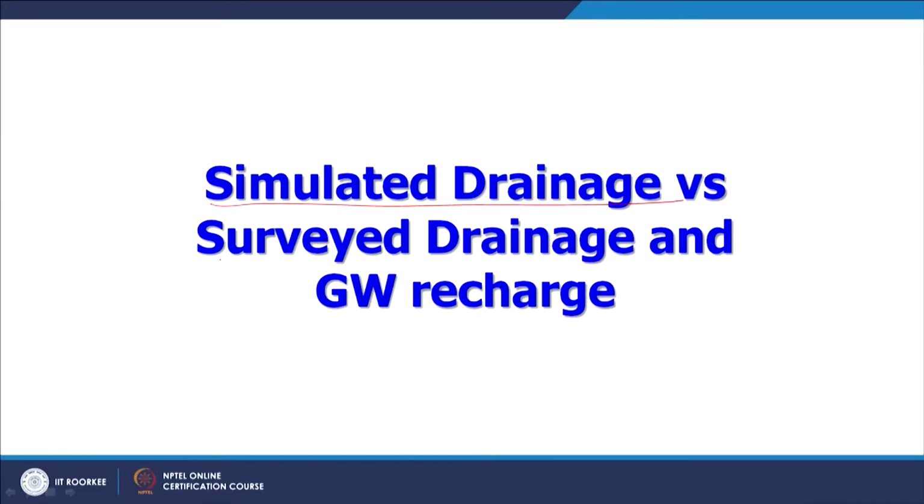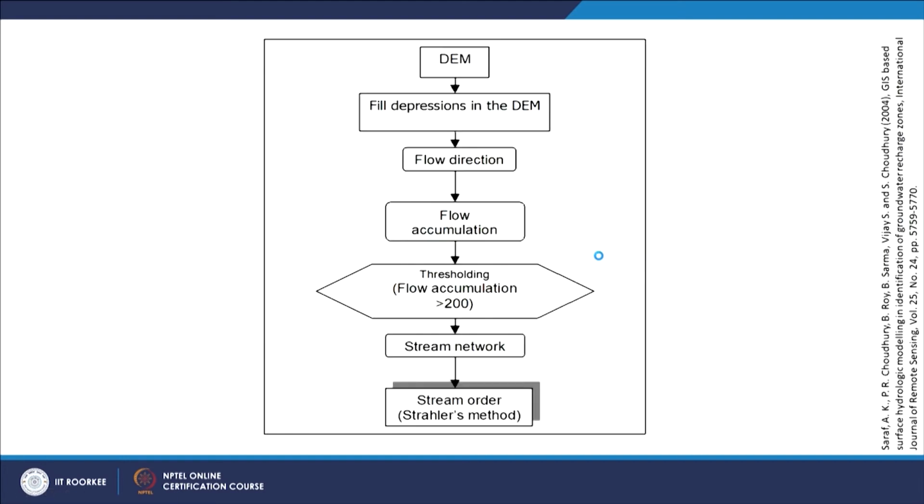So, basically we have to compare a simulated drainage versus surveyed drainage. Surveyed drainage is the real one, which can come from survey toposheets, and we can get an insight about groundwater recharge. This part we have already discussed in surface hydrologic modeling: you use a DEM, you fill it, flow direction, flow accumulation, thresholding, stream network and stream order.